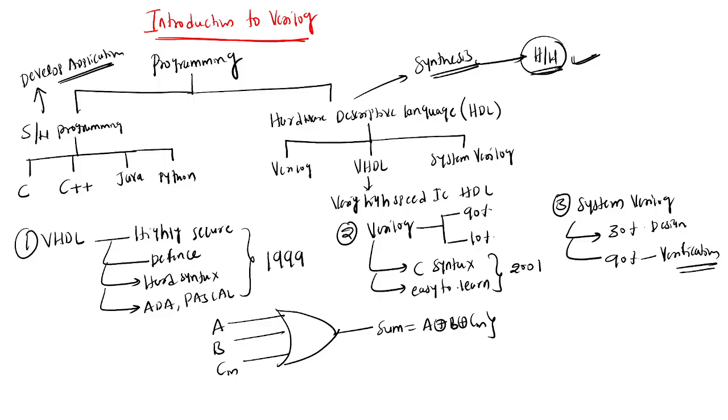But by applying programming, how do we verify this? You need a verification language, and we use SystemVerilog for verification. But if you write a test bench for I2C separately, and then for UART separately, there is no standardized test bench.